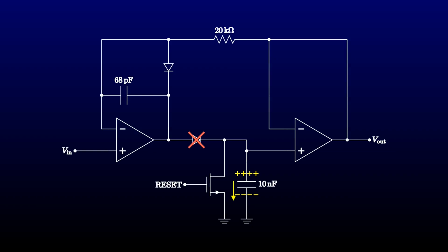That leaves just the transistor and the diode as possible leakage current sinks. But here we start running into problems with the component data sheets. The manufacturers often don't tell us realistically what leakage currents to expect. They lowball the device's capability, often by orders of magnitude. Now, mind you, I know the risks of going beyond what the datasheet offers. If you do so, you're pretty much committed to incoming inspection of all your parts. I think I can offer you some options that are datasheet compliant, but there are others that a small-time player can certainly get away with. We'll start with the diode.